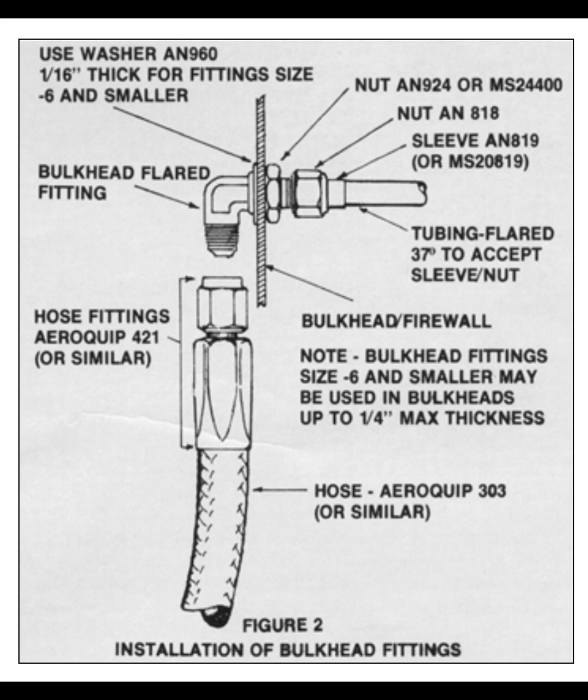What are the three parts of a military standard tube fitting, MS? Body, sleeve, nut. What will be the result of over-tightening a flareless tube fitting? The compression sleeve's cutting edge will cut too deep into the tube, causing the tube to be weakened.